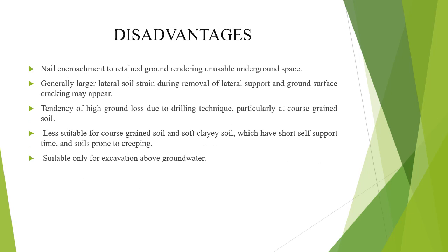Now, disadvantages. Nail encroachment into retained ground, rendering underground space unusable. Generally, large lateral soil strain during removal of lateral support and ground surface cracking may appear. Tendency of high ground loss due to drilling technique, particularly in coarse-grained soil. Less suitable for coarse-grained soil and soft clay soil, which have short self-supported time and soil prone to creeping. Suitable only for excavation above groundwater.